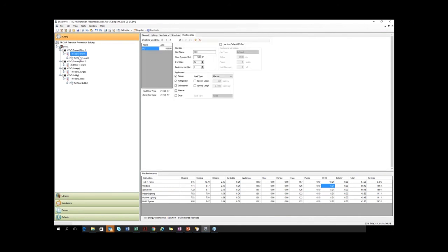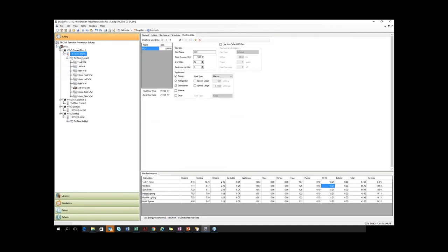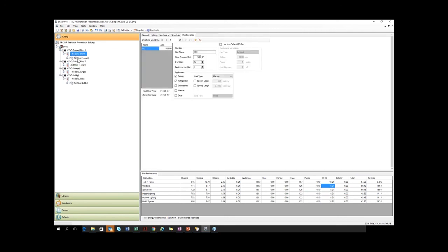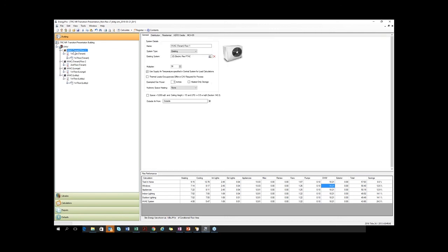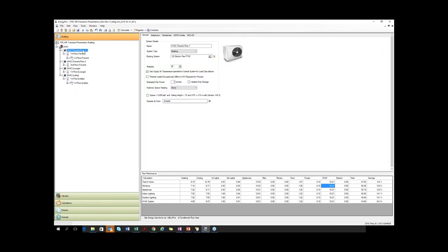Yeah, so that's pretty much the whole procedure for transitioning the models. A couple more items just to look out for are, like I said, the DHW system. Make sure that's there. Make sure you size all of your equipment or input the rated size, except for the fans.